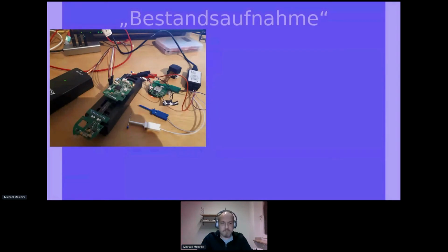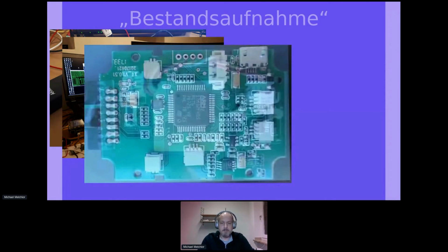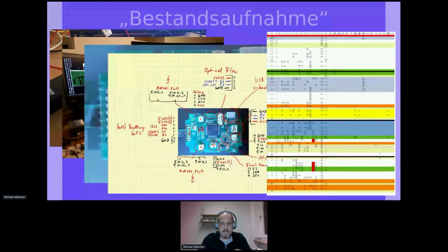So I started poking with some needles all those ports. I took some pictures, put the board under a microscope, put those pictures front over each other, and started tracing or following the traces, some sketches, and I ended up with an Excel sheet that had the pinout of the whole chip. And also all the interfaces, I was able to get the baud rate for the UART and everything.